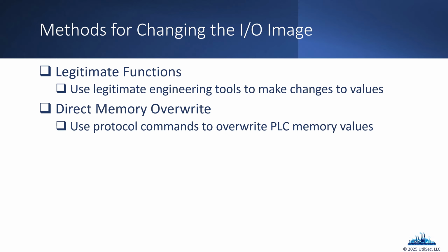Now I see a lot of default passwords still in OT. If I remember it, the default password for the Click PLC is Click. Makes sense, right? It's probably the one you would guess. So if you don't change the password, default passwords are still a thing, even in OT. We see them everywhere in IT, and we see them everywhere in OT.